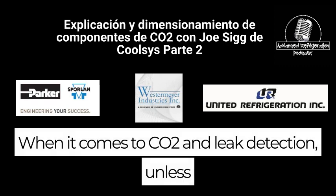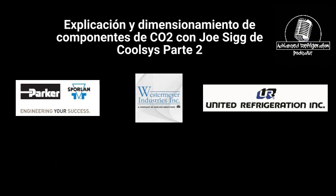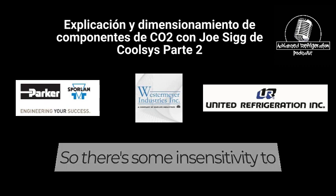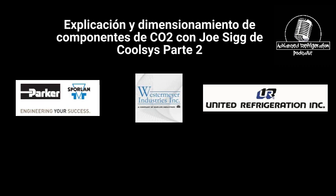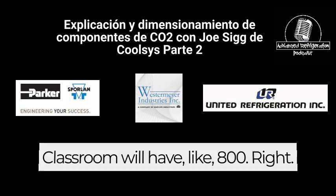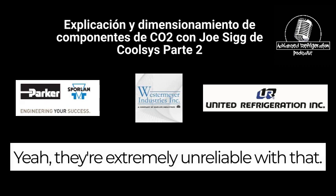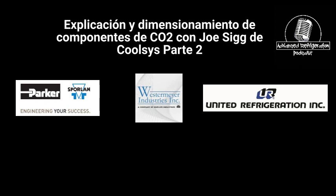When it comes to CO2 leak detection, unless you have a drastic leak, the leak detectors are not going to pick up on a leak. It's gotta be like a dump because you've got people walking through these spaces, breathing out CO2 all the time. So there's some insensitivity to CO2 inherently in the detectors. Normal spaces have about 400 to 600 parts per million. A classroom will have like 800. They're extremely unreliable with that. It's got to be just absolutely blowing. It's gotta be a dump.